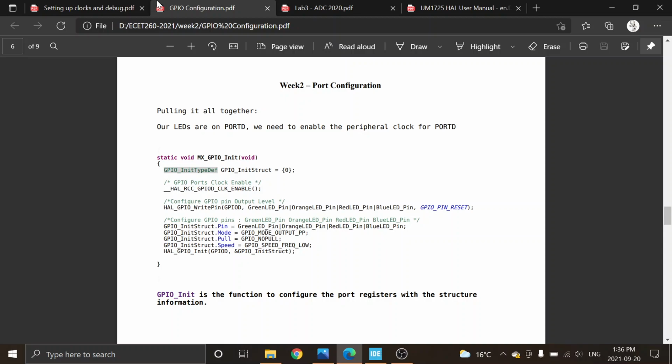This is good for most uses, but if you find that the software is sluggish in areas, you can go closer to the bare metal of the CPU, to the CMSIS layer or the low-level driver layer. The closer you go down through the layers, the less abstract it is. So if you needed to change to a different micro in the family, there's more tweaking you have to do to go from one to the other. Whereas if you call the HAL layer, it's supposed to move across all the Cortex families. From the F0 to the F4, if you've initialized port D, it'll work across the range.